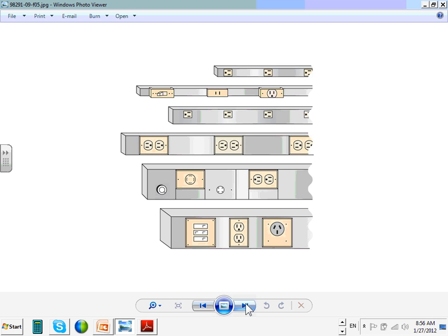Now a special type of raceway, guys, is the multi-outlet assembly. Manufacturers took a raceway, like the one in front of you, and pre-manufactured receptacles or switches or low voltage parts, and put them in the raceway, and they call that a multi-outlet assembly. To make installation easier, you plug in the surface mounted multi-outlet assembly, or wire it hardwired. The one in front of you, Chris, is plugged in, but you can also have a hardwired one. You can have low voltage and high voltage, two sections, one for high voltage and one for low voltage on the multi-outlet assembly. So what's the difference?